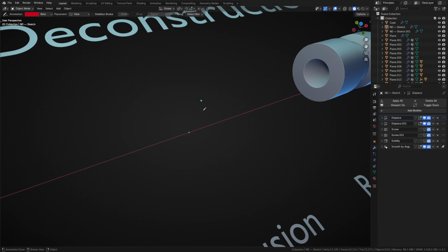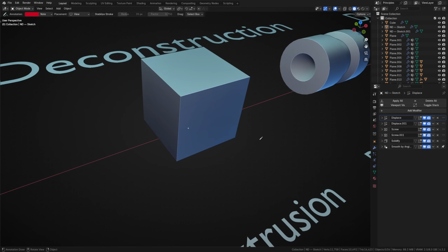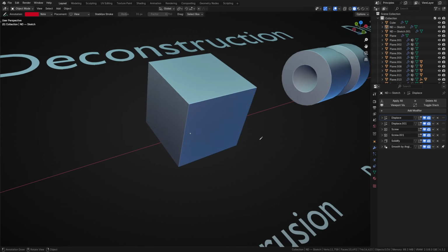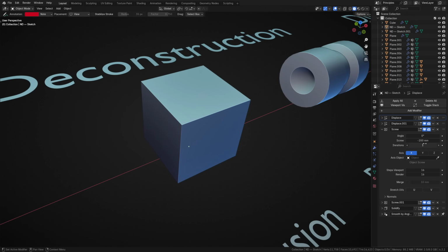Given all of this, we now know that if we wanted to create a cube non-destructively, we could pick any one of these simplified forms and perform one or more extrusion operations, resulting in the final geometry. Producing the shape by stacking one or more non-destructive operations allows you to change the parameters of those operations later, resulting in new computed geometry without manually tweaking vertices, edges, or faces. This, in its simplest form, is non-destructive modeling.